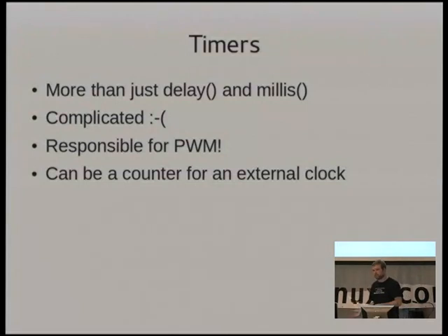And what the Arduino library is doing and abstracting away from you when you do that analog write on a digital pin is it's actually setting up a timer in the background that matches the setting that you have there. So if you've done 128, it sets up a timer and says, I want you to toggle every n milliseconds. And then it links it with the output pin that you've just done in hardware, and every however many milliseconds it is, it'll toggle the state of that pin.